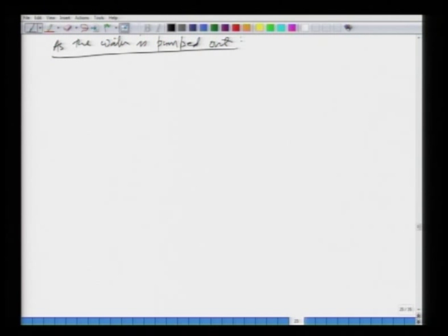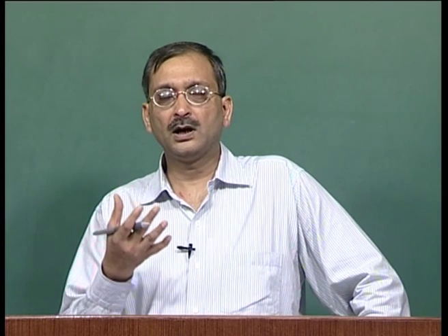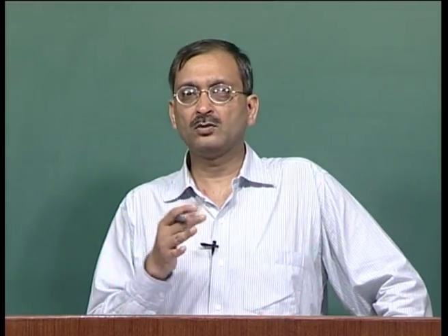So, we are going to look at a few things. First of all, as you pump the water out from an unconfined aquifer, initially the flow will be steady or unsteady? As you pump the water out, you just started pumping water out at a certain rate, which is constant, let us say. So, the drawdowns will be changing,